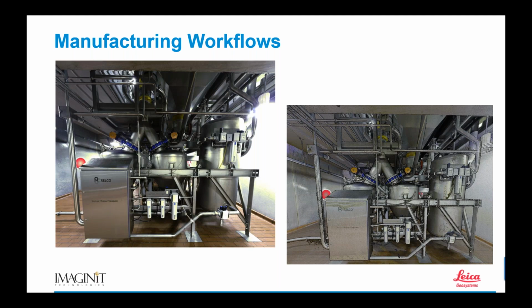What I'm talking about today is from the building, equipment layout, and floor layout realm of our industry. That is LiDAR scanning, where we're getting accuracies down to 1/16 of an inch and a range of 130 meters, or 390-ish feet. When we look at the other side of the spectrum, where I've got to get sub-millimeter accuracy, that's a different kind of laser scanning called reverse engineering. That's where we get into tracking arms and tracking scanners, which get me down to sub-millimeter accuracy. It is two completely different worlds.